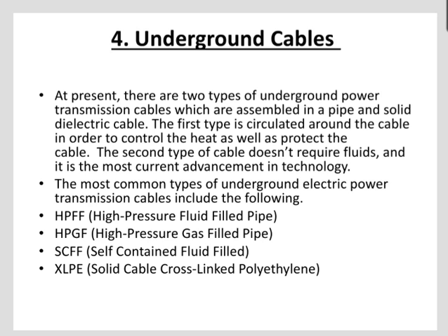Disadvantages of undergrounding: it is more expensive, as the cost of burying cables at transmission voltage is several times greater than overhead power lines. Finding and repairing overhead wire breaks can be accomplished in hours, but an underground repair can take days or a week. Underground cable locations are not always obvious, which can lead to unwary diggers damaging cables or being electrocuted.